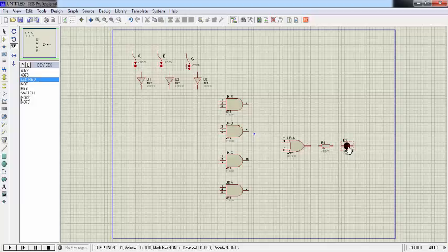For the LED diode, we need a resistance between 220 ohm and 470. It's the interval for the LED to work, because the LED mostly needs between 2.7 and 3.5 volts, from 5. Okay, to wire it is just to,